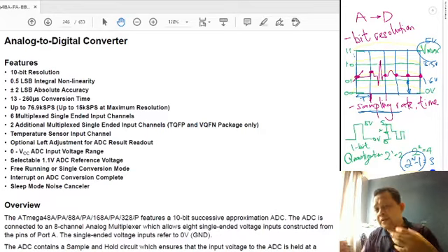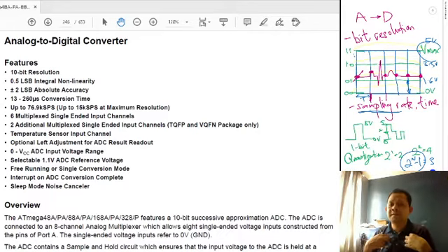We cannot set our ECG signal when we place electrodes, so you cannot set it to go on 1.6 or 0 volt, because this is a real signal. You cannot expect your baseline voltage for your ECG to be the same as mine. This is the analog world, and it's very, very different.